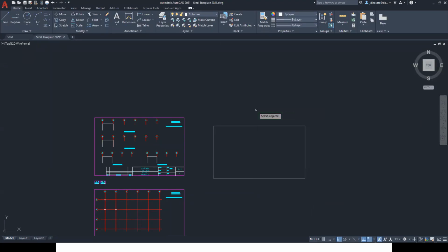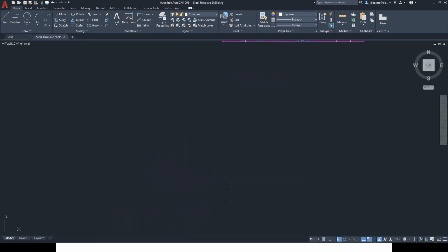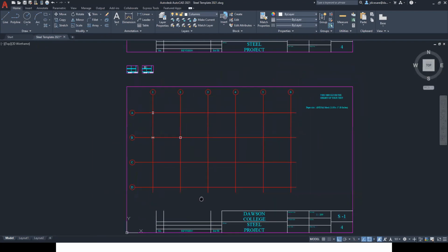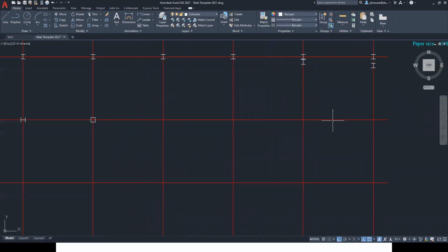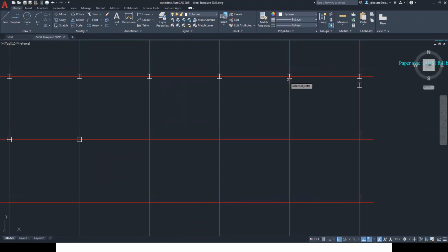Okay, do yourself a favor. Remember what is typical. So, for example, when you say copy, I copy. Oops, sorry. I forgot to go perpendicular. I did nearest. I wasn't paying attention, so I'm going to have to erase.